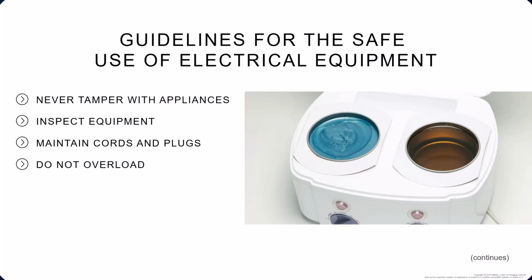Inspect all electrical equipment regularly. Keep all wires, plugs, and electrical equipment in good repair. So do not use cords that have exposed wiring in any part of the cord or where it attaches to the appliance. Use only one plug in each outlet because overloading can cause a circuit breaker to pop. And if more than one plug is needed in an area, use a power strip with a surge protector.